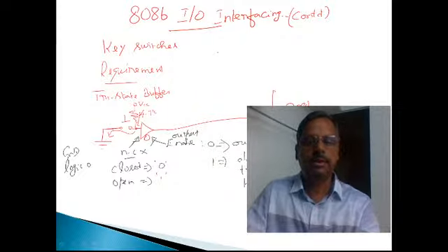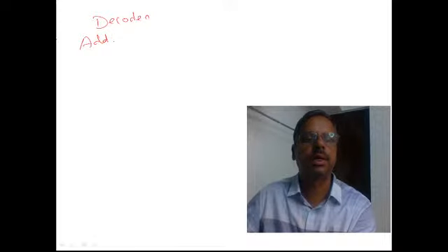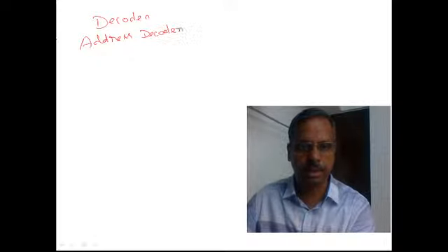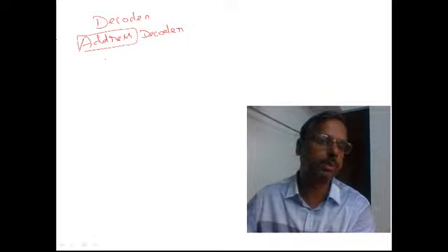Before which, I think I have already told you about decoder logic in the last class. But anyway, let us recap that particular thing. We need to have a decoder. Basically, what we are going to decode is the address, so that the tri-state buffer gets selected only when a particular address pattern is coming here.